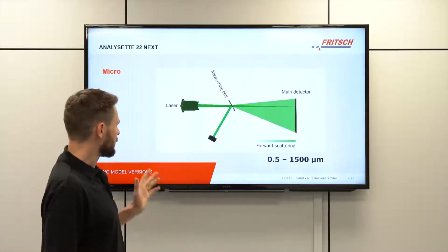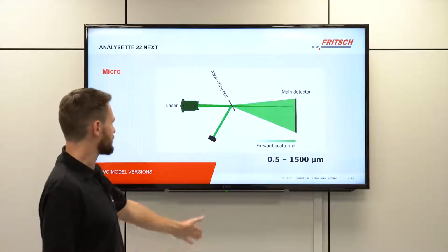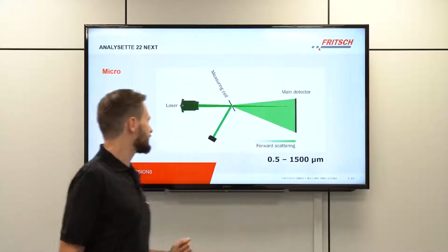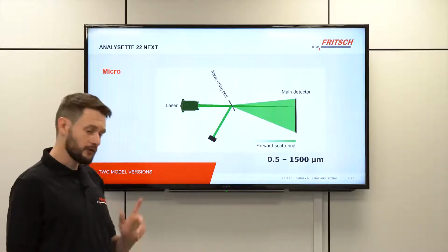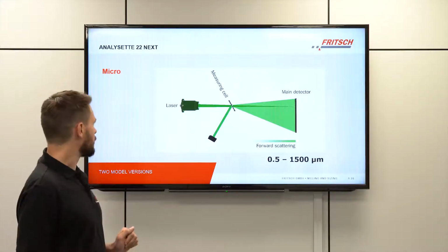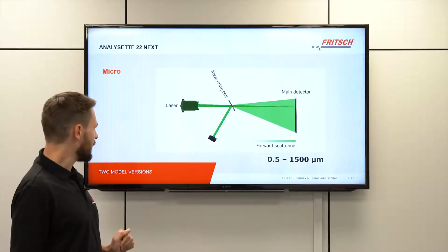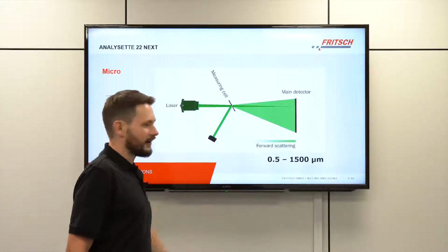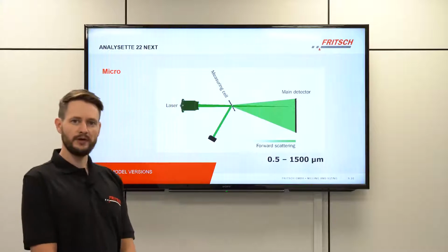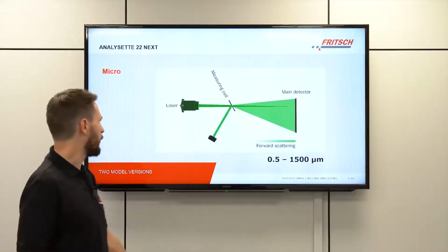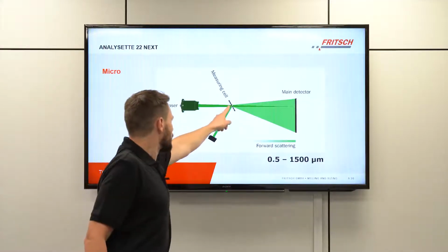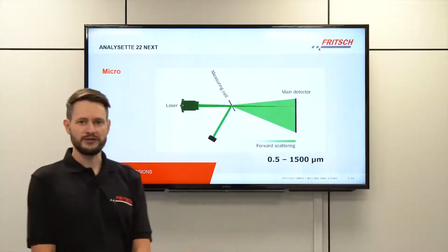And maybe the most important part is then our detector, which basically recognizes the light intensities of not only the scattered light but also the main laser beam. And on the bottom we find a monitor diode, where we can also constantly check the laser output power by the reflection of the laser at our measuring cell.